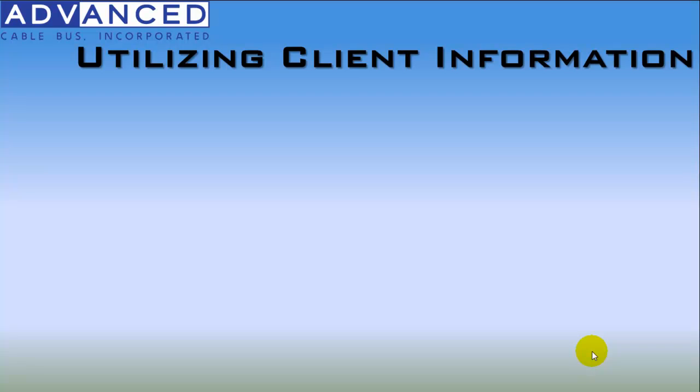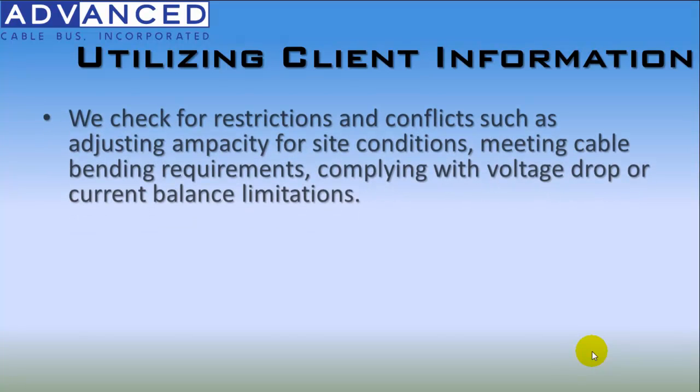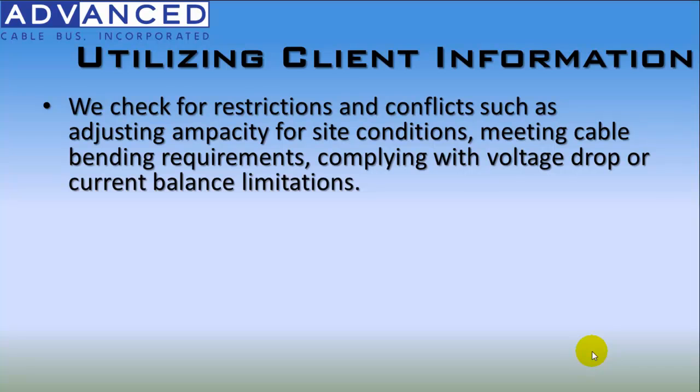So first we will utilize our client information in order to successfully come up with a design. We sometimes have to adjust the ampacity of the cable bus system for the site conditions. And this occurs when you have, for example, a job site that has unusually high ambient temperature, or a job site that is near an active heat source, such as a very steamy factory.